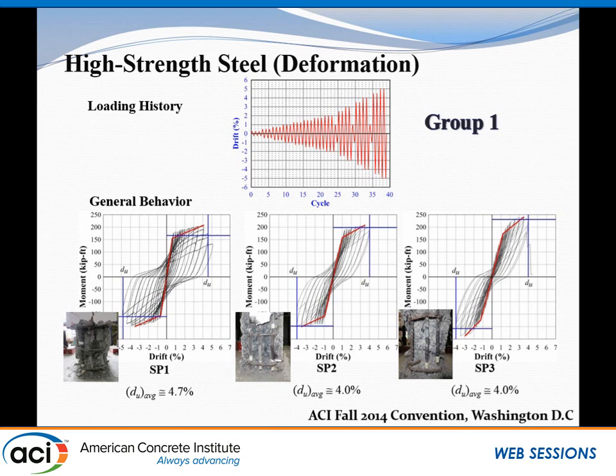You can see that the spacing of the transverse reinforcement seems a little bit wide. The spacing in specimen SP1 is around 6 db, where db refers to the rebar diameter, but it is around 8 db in specimens SP2 and SP3. Despite this wide spacing, specimens SP2 and SP3, reinforced with high-strength steel, achieve 4% ultimate